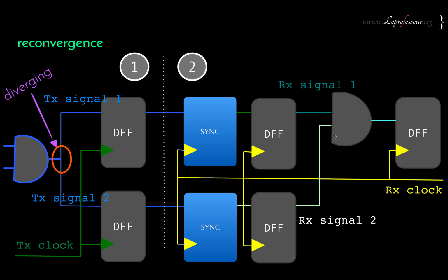So here at this point, the signals are diverging. This is the output of one AND gate diverging to two clock domain crossing signals, going to the receiving clock domain and getting combined again, or converging again. Very bad design practice, very bad. So this is what reconvergence and divergence mean. Signals are diverging and then converging. We need to deal with this. It's not very good in this fashion.